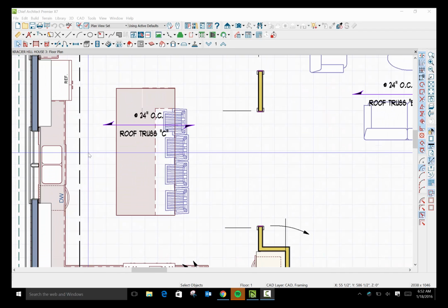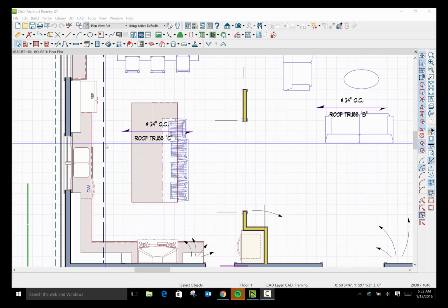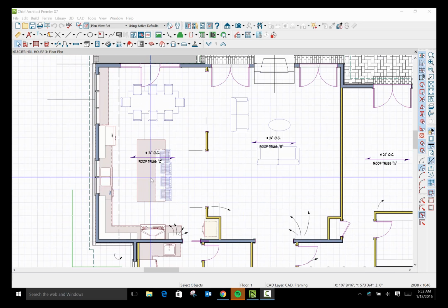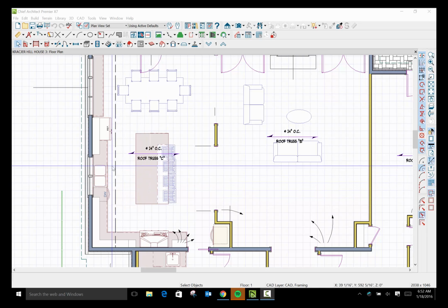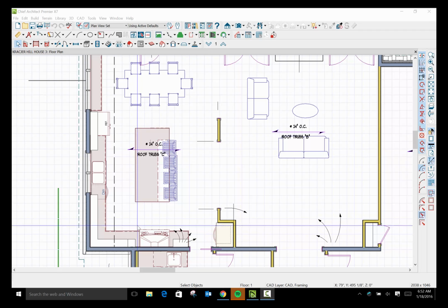Couple of design tips. Here, minimum 3'6", maximum 5'. You want to be somewhere in there, 42 to 48 inches. Really nice dimension. Five feet if you really have a big kitchen. I had 5 feet in my kitchen a while back, and I had an 8-foot counter, kind of like this also. It works well, especially if you have someone working here, someone working there on the island, and that sort of thing.